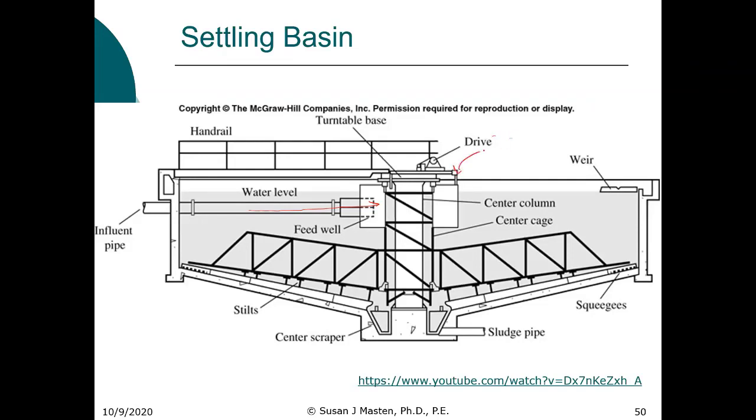add ferric chloride. And that's added because of the organic matter that is introduced from the water, they recycle water from the sludge lagoons. That has a fairly high organic matter content. So they add ferric chloride to remove that NOM. It's not necessarily the case in all plants, but this is what they do in the East Lansing plant.